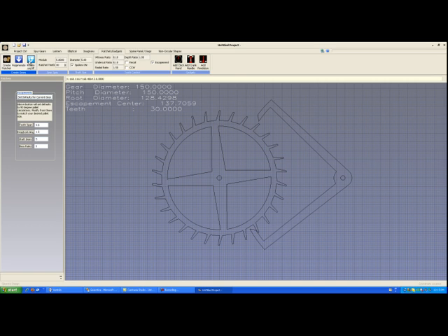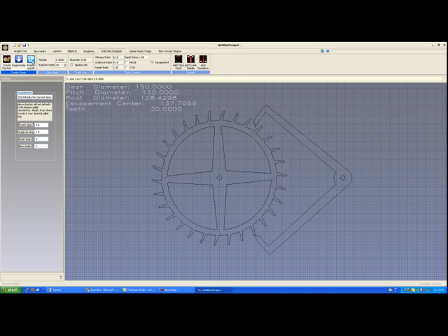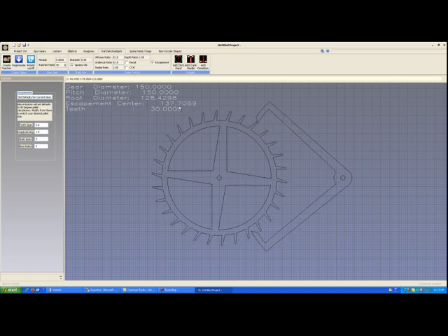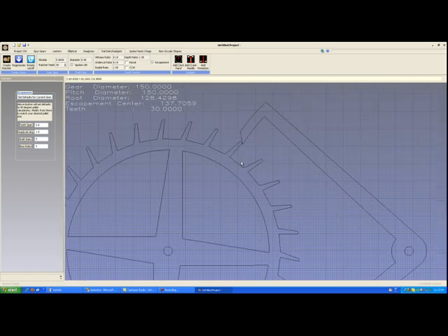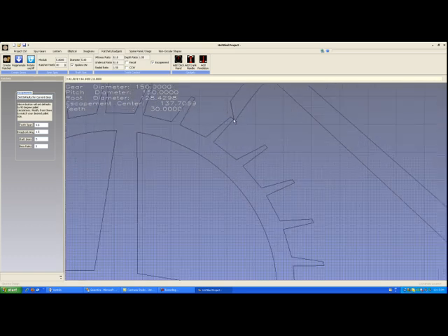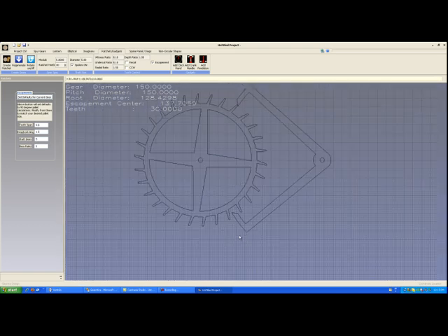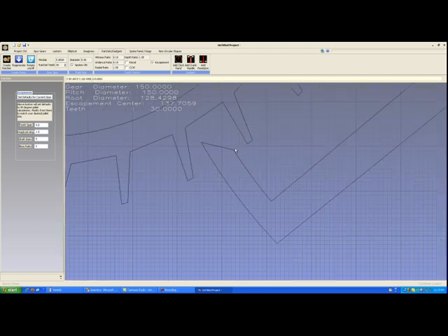Well, let's take a look at this tooth on the pawl as it rotates. As you can see, the top tooth is about to come off of the pawl. In another split second, this tooth is going to swing free of the pawl, and the deadbeat is going to have a tendency to snap forward. It's going to snap forward until this bottom tooth hits its pawl. That drop is the drop angle. How big of an angle does the deadbeat swing before it hits the lock face? That's the drop.